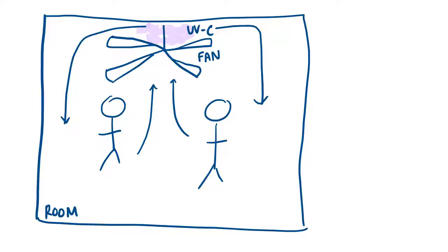So is this a perfect solution? No. As I showed you in the picture before, the fan pulls air up and then pushes it back out into the room. It's very likely that the room is not completely mixed, and therefore our number is not completely accurate. However, we can do an analysis like this to get a good idea of how well the fan will work in our situation.